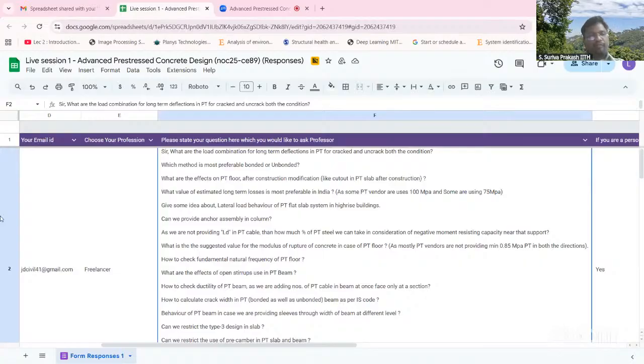Again, we discussed this in the last lecture, how we can do structural strengthening using external PT. There we showed all the case studies. So that also can be done. Or locally, if you want to strengthen that, probably the easiest way as an additional reinforcement is putting an FRP sheet, right? That'll kind of stiffen things up, right? Or put a steel beam.